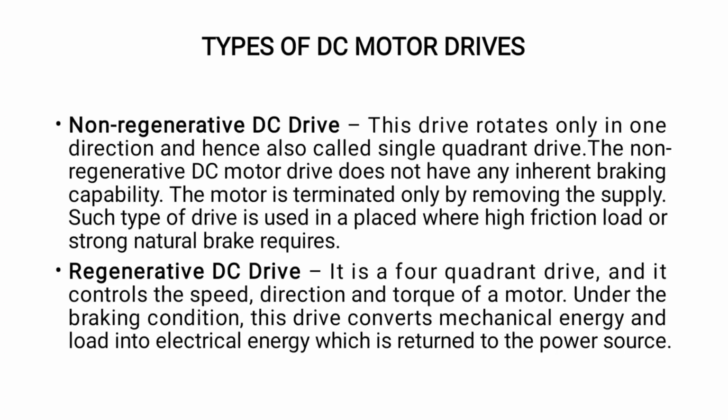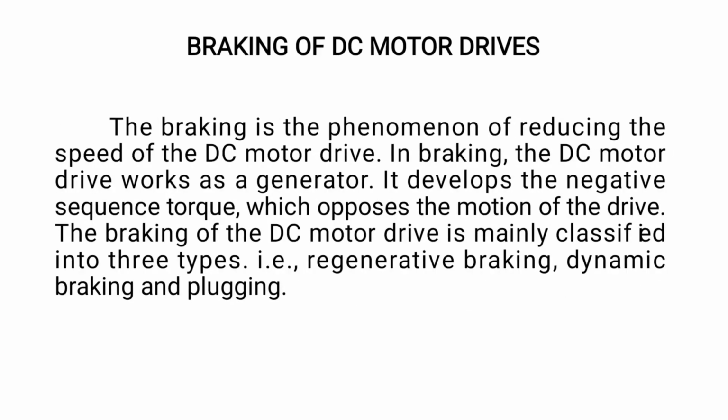Regenerative DC drive. It is a four quadrant drive and it controls the speed, direction and torque of the motor. Under the braking condition, this drive converts the mechanical energy of the load into electrical energy, which is returned to the power source.